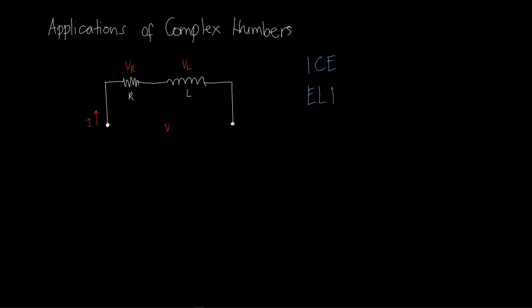Okay. The current, I, right? Current in the capacitor leads the voltage. It comes first, right? It was written first. So in the inductor, the voltage in the inductor L leads the current. So voltage comes first compared to current by, of course, 90 degrees.